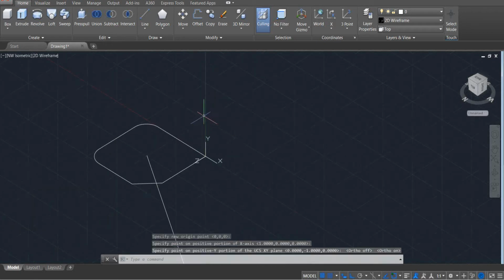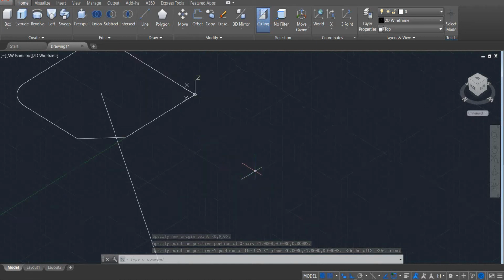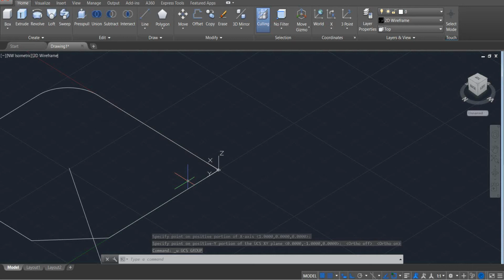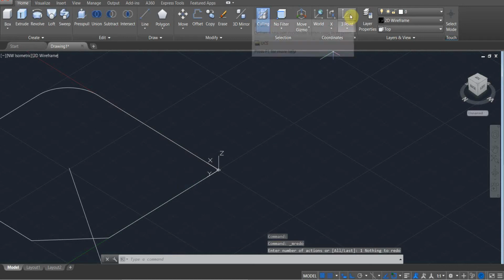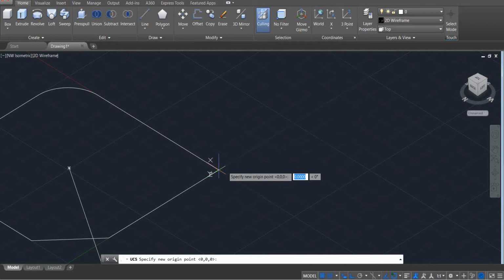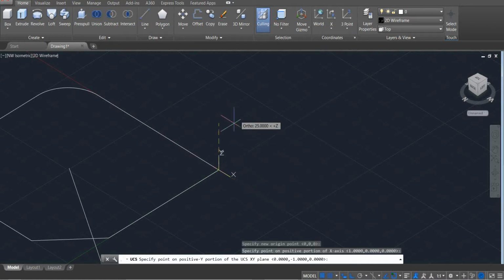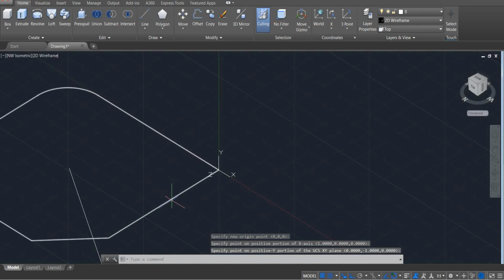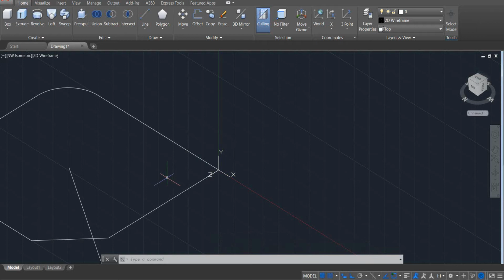So if you click up, as you can see, I moved the XY plane. Initially, the XY plane was over the horizontal plane. Now, when I move the UCS, again, I'm just going to repeat it, 3 points. Make this the 0 point, 1 point over the positive X, 1 point over the positive Y. This gives us, like we already moved the XY plane to be vertical, standing, instead of being horizontal.